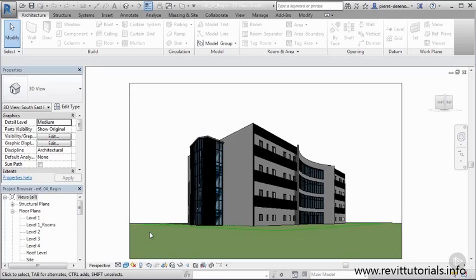So first of all, we went ahead and worked a little bit ahead, and we made some adjustments to this topo surface. I want to show you how a site element we can add that we can use to add concrete, paving, sidewalks, and things like that. So what we'll do is we'll actually split the surface of this topo surface we have and create concrete. And once we get that done, I'll show you how we can add some trees and people with ease.